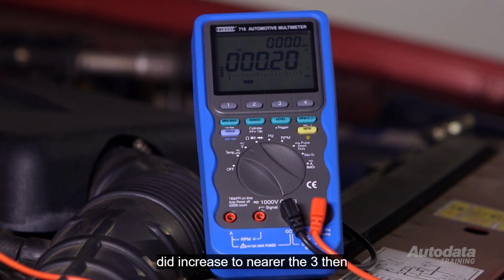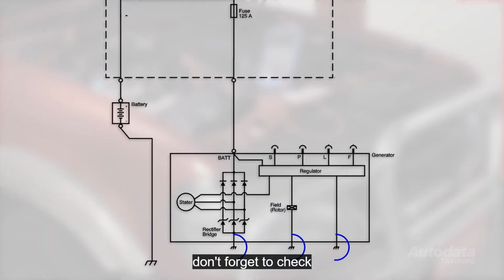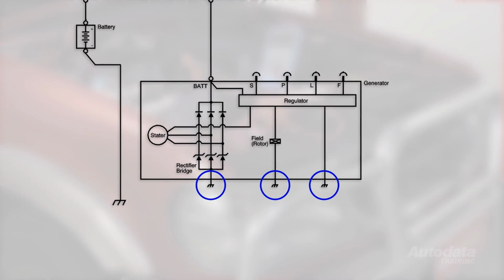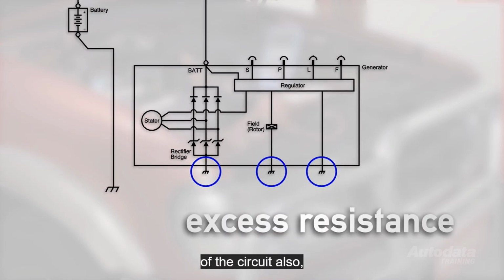If the voltage did increase to nearer the 3%, then you would have to check for excessive resistance in the cable. If the positive side of the circuit is okay, don't forget to check the ground side of the circuit, as this will connect the alternator to the negative terminal of the battery. There could be an excess resistance in this part of the circuit also.